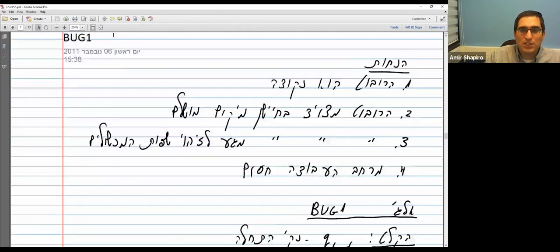If my configuration space is the plane, and I want to travel from one point to another in the plane, and my robot is just a point with only a position sensor and a touch sensor that touches when it hits an obstacle, and my workspace is closed and finite, not infinite, then there is an algorithm called bug1. Then I'll show you the bug2 algorithm.